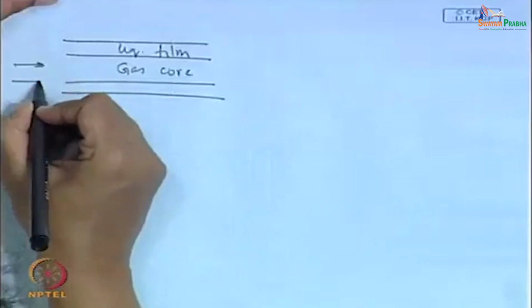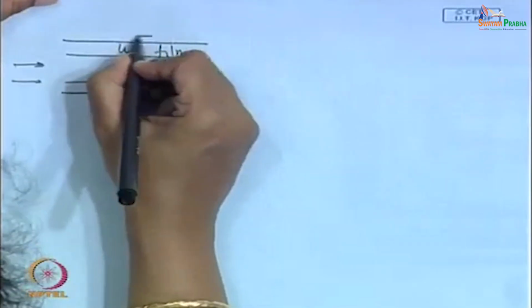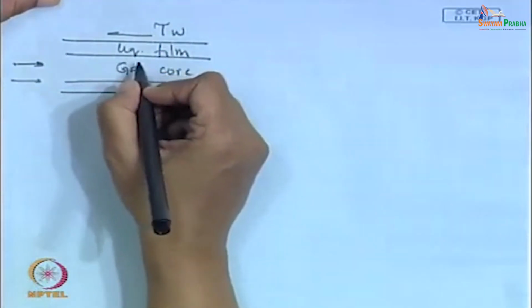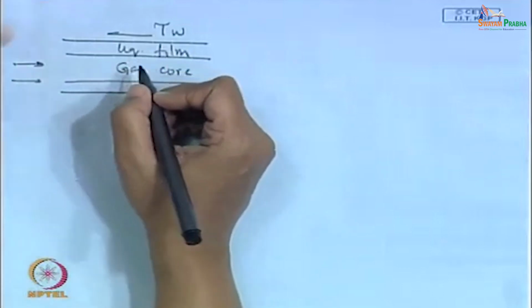So, for such an annular flow situation, if we can represent it, it is sort of this. I have drawn very straight lines. This is a gas core, this is a liquid film. If flow occurs in this particular direction, then wall shear stress will be in this particular direction, and there will be a tau I, the interfacial shear.